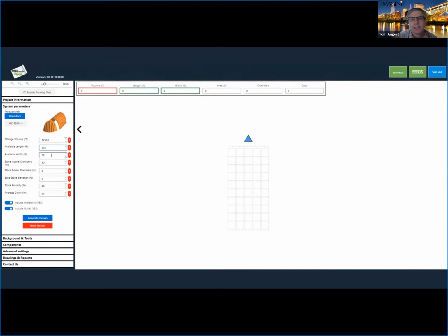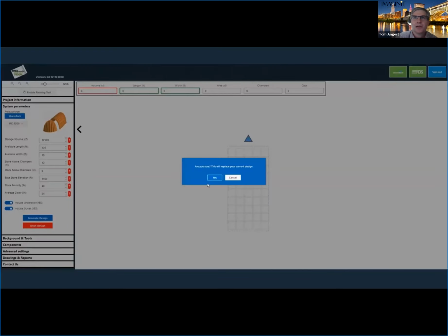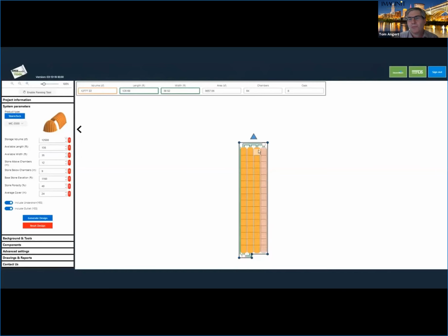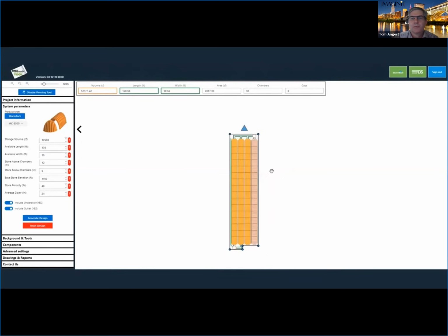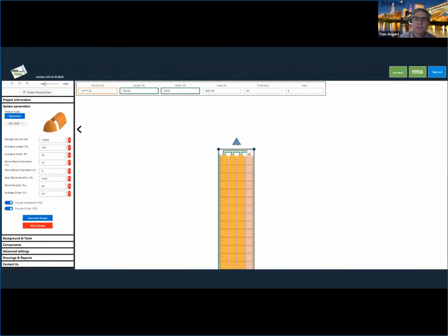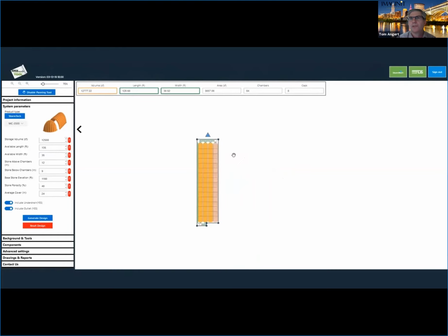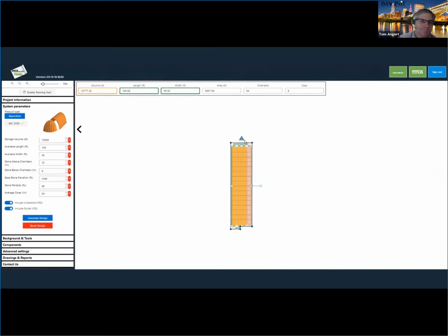So basically, when somebody's putting in a parking lot or parking garage, where you're preventing rainwater from absorbing into the ground, you don't want it running off and flooding everything. So they have products, chambers and pipes that they put under the ground to store that rainwater and let it slowly leach into the ground.